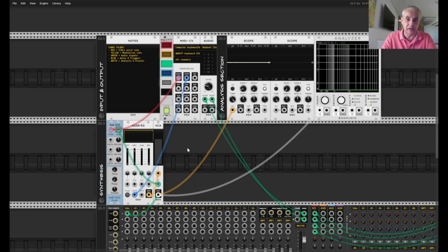Therefore, if you need to avoid aliasing, I would recommend using a sawtooth that's not mathematically entirely correct. It is not necessarily fully alias free, because in the high frequencies you can still get some aliasing popping up, but in the general musical application of a sawtooth wave, you can pretty much stay away from any aliasing artifacts.